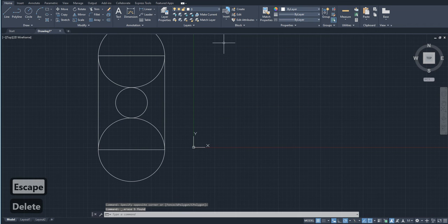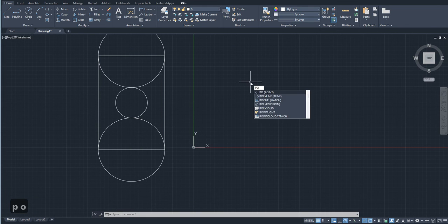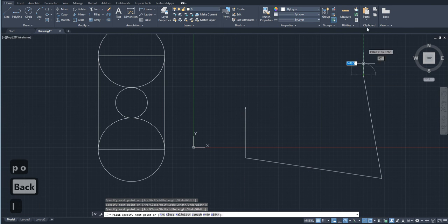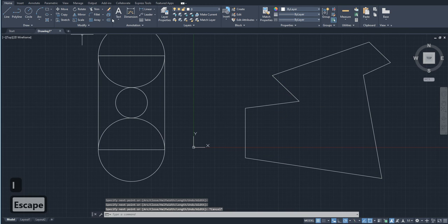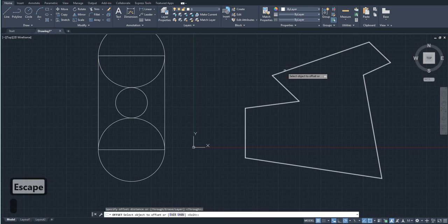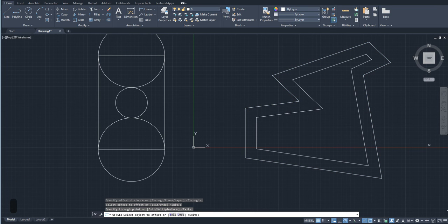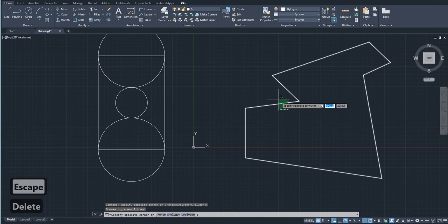So that's all about the offset command. The next thing I'm going to be telling you about is polylines. We already discussed polylines. I just entered the command for that, PLINE. The offset command also works for polylines. Likewise, it works for basically any objects, but say this line is not a polyline, these are different lines.